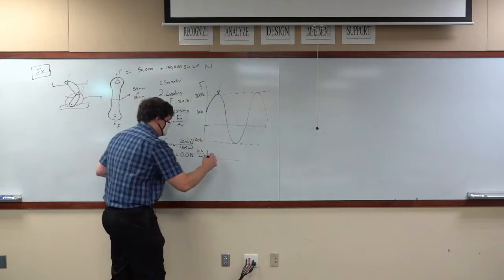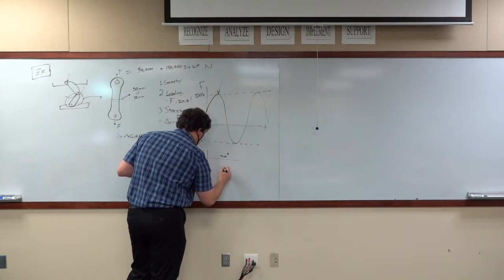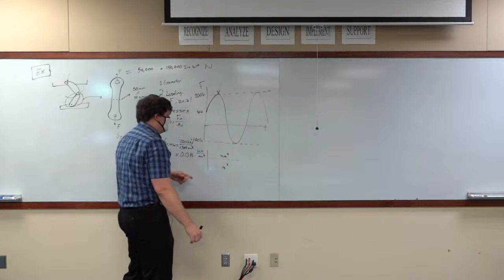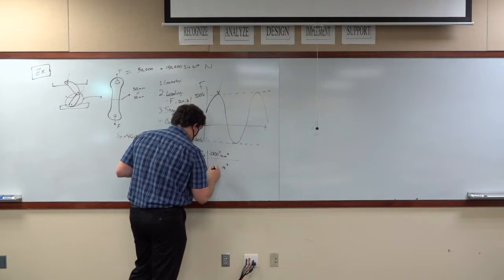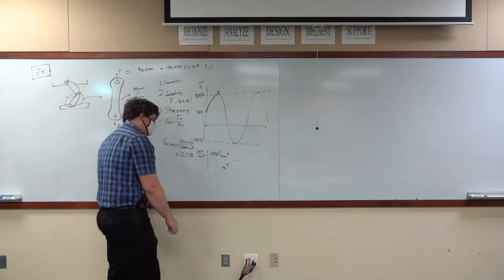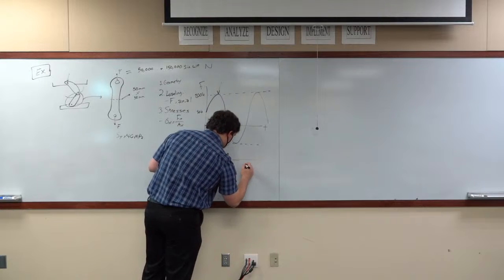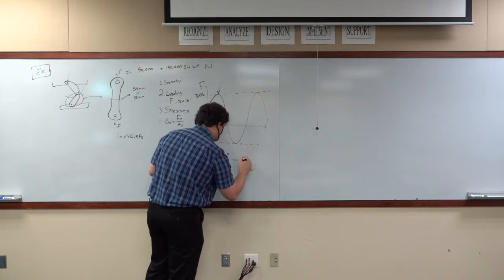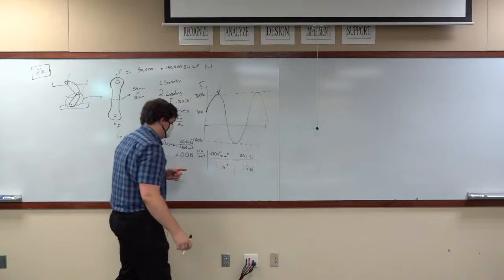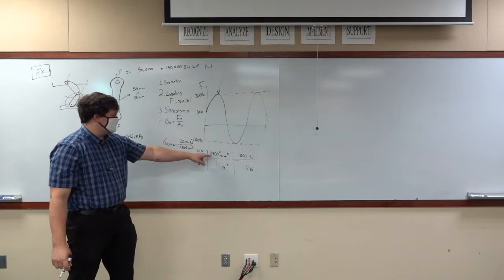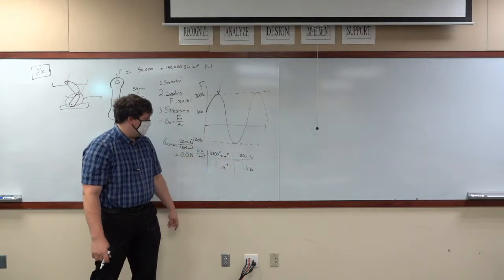So if we multiply this by however many millimeters squared are in a meter squared, which is 1,000 squared, and then divide by the fact that 1 kilonewton is equal to 1,000 newtons, ultimately we take this number and multiply it by 1 billion.